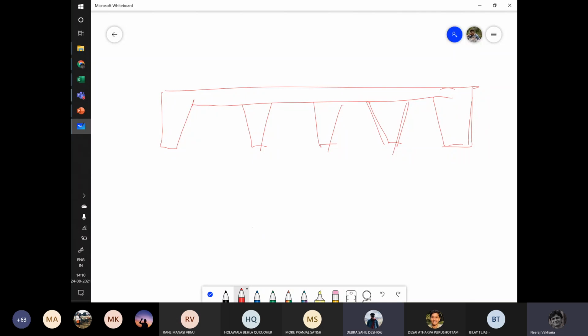Probably we can take the entire depth till the rib and then subtract these small cuboids. Yeah, that is one way. But to consider a 3D trapezoid and calculate its volume, as you said, you will consider the whole depth. Let's say it's 400 and this is 10,000 mm. You will calculate the whole volume by 10,000 by 10,000, and you will calculate the volume for one block,